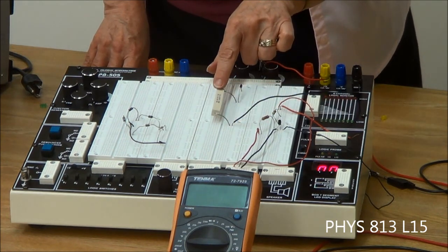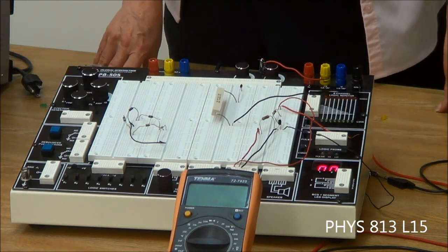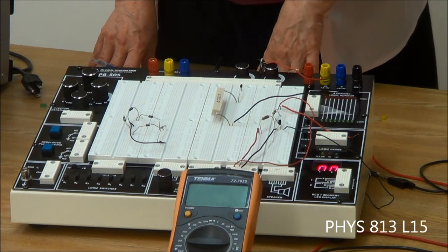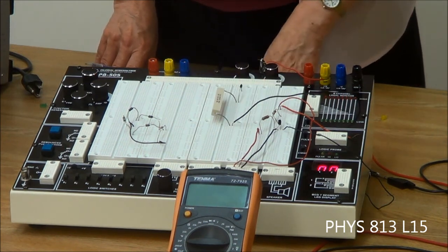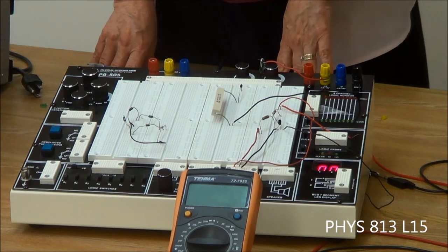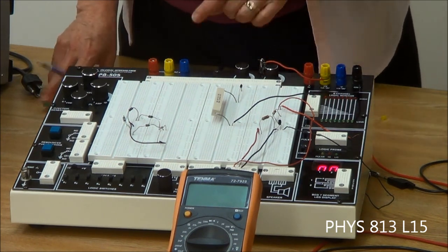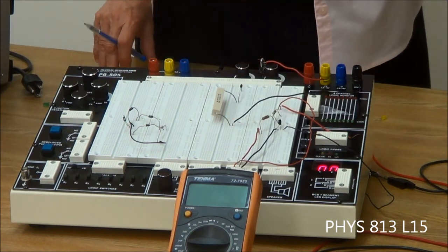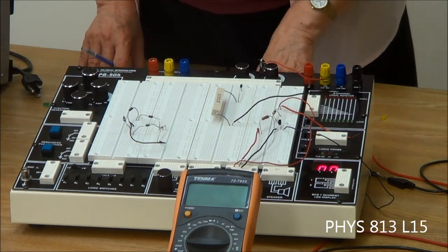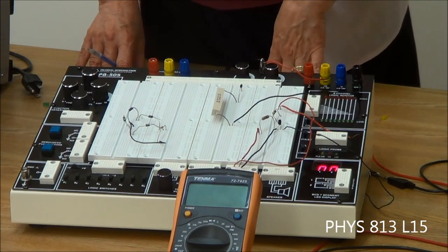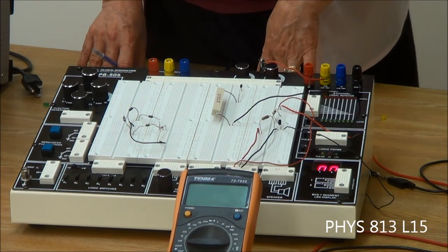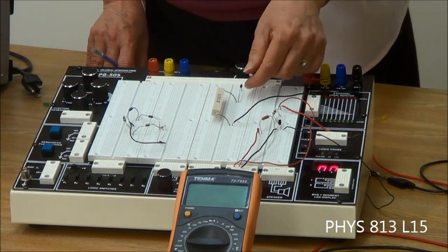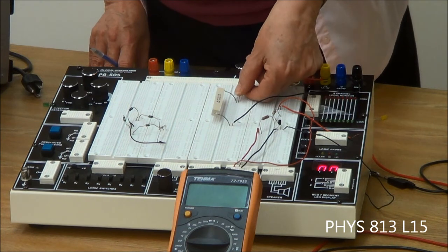And then this one is the 50 ohm power resistor. It's a rectangular block, I guess. It's a lot of ceramic, and it's designed to withstand a lot of heat. So that's why we have that one. The leads to it are a little bit bigger than the resistors and these other wires, so it's a little harder to get them in the holes. Just be gentle, but you still have to push hard enough to get it to fit into the hole. So I've got it in there and in here. Now this one, I think I'll bend it a little bit away like this.